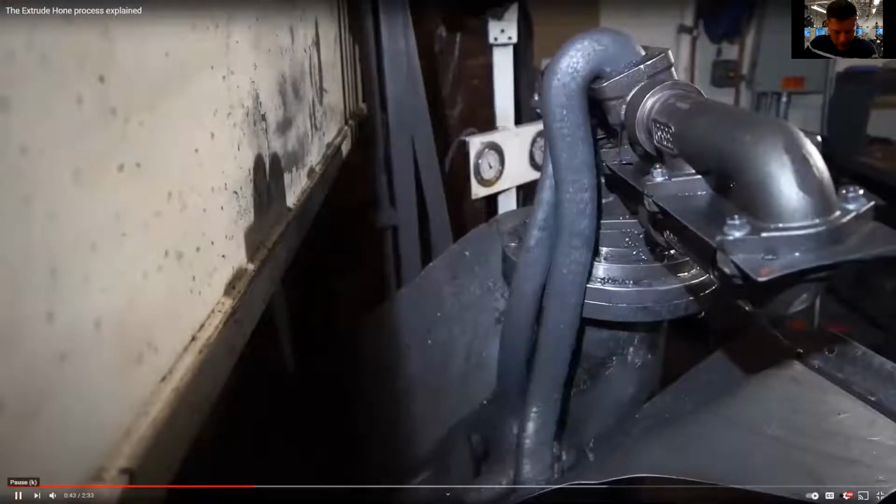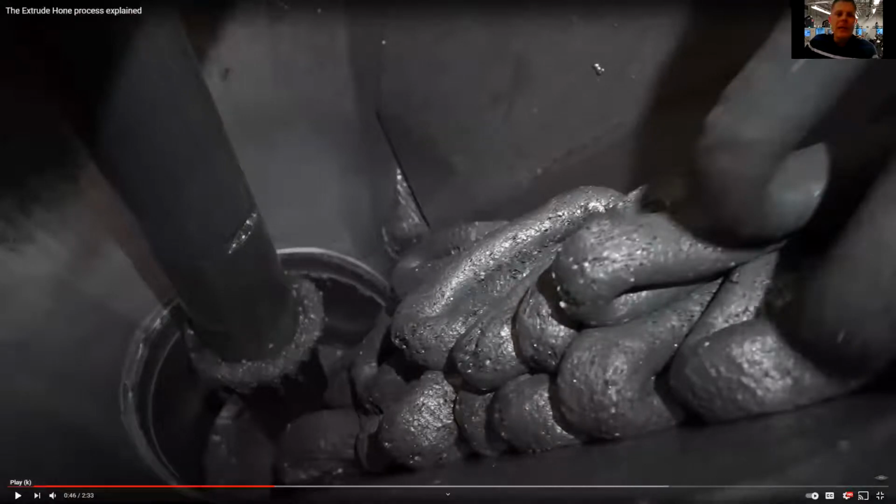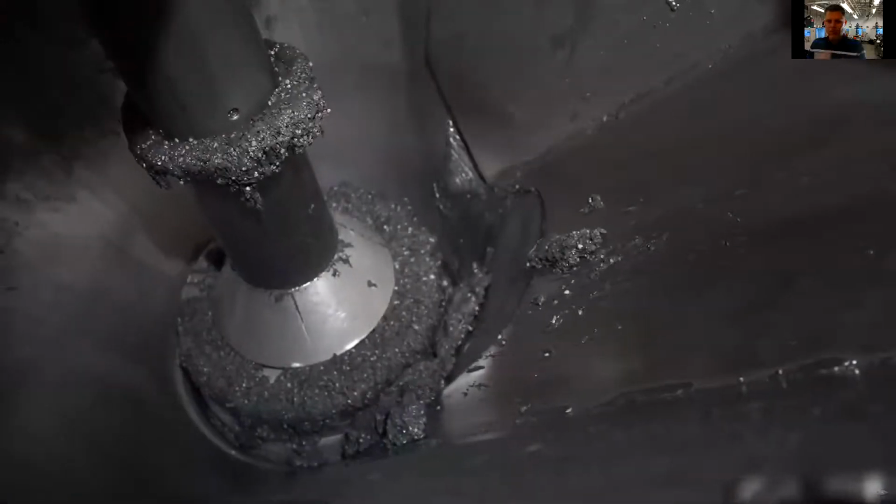All right, as you can see behind me here, this is the technique called abrasive flow machining. They're pumping media material through the internal portion. They reuse that media, by the way. It goes back down into the floor where the piston is, and they push it through the manifold, smoothing out all of the porosity. It's being forced through the manifold.